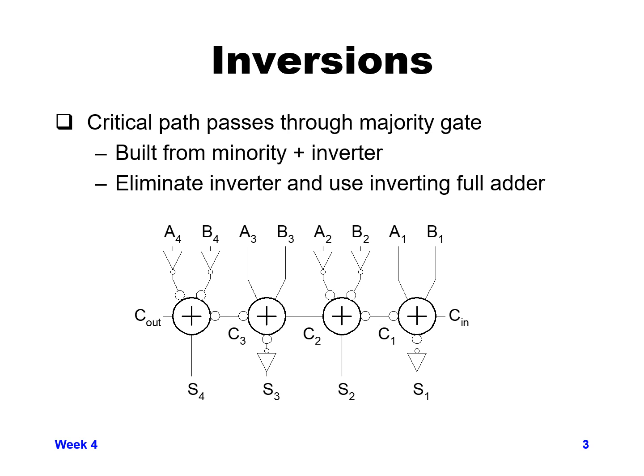So this is showing, well, what if we created stages where we have one stage that takes C in, it gives us C out bar, and then we make the second stage actually accept C out bar as its main input, and then it generates a C out, which is our second carry bit. Every other carry bit is going to be either even or odd, and you just keep inverting it stage by stage. So this can eliminate an inverter as compared to our normal full adder.